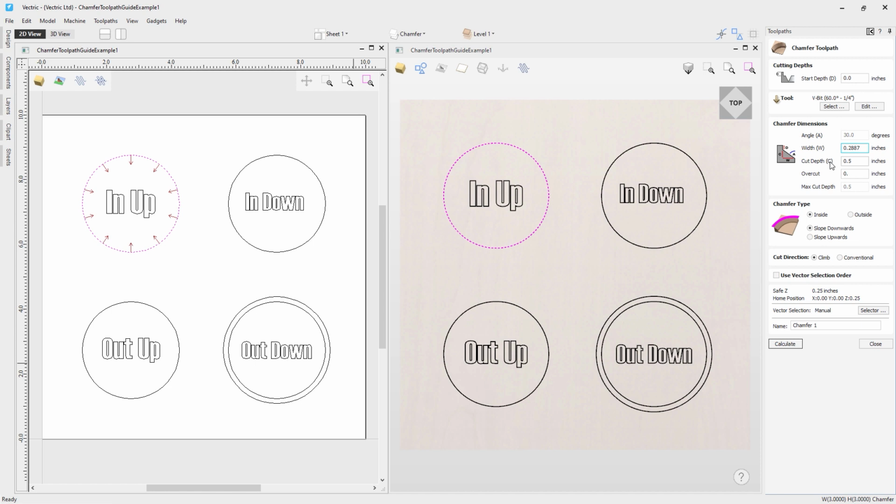If you're using a round tool, then this value is a little bit more than the cut depth specifies, as it has to consider the fact that we're using a rounded tool and has to cut a little bit deeper to achieve the requested width or cut depth entered. But we'll look at that a little bit later in a different example. But as you saw a second ago, that same thing applies if we decide to apply a bit of an overcut, and we'll need to go just slightly deeper in order to achieve the full cut depth.